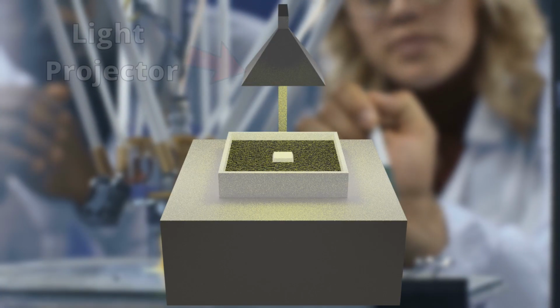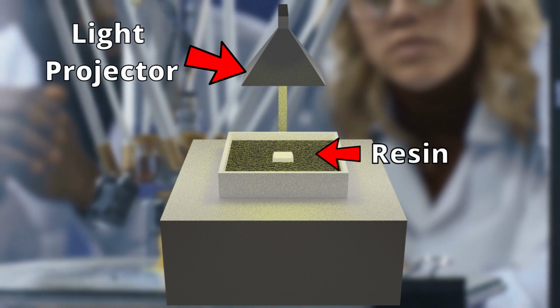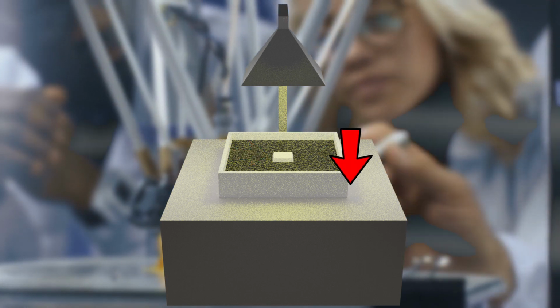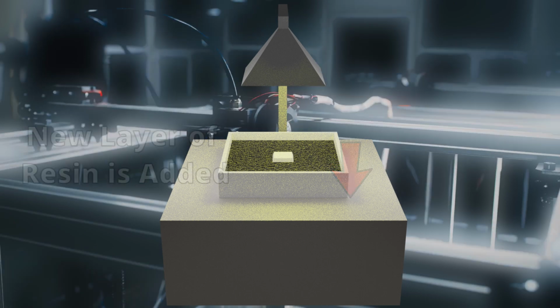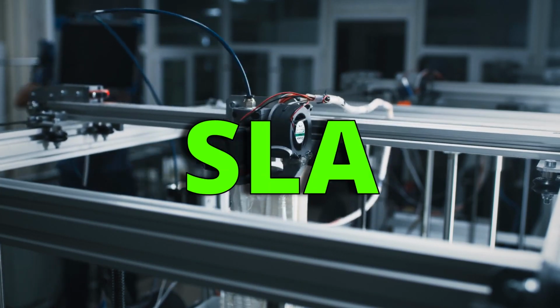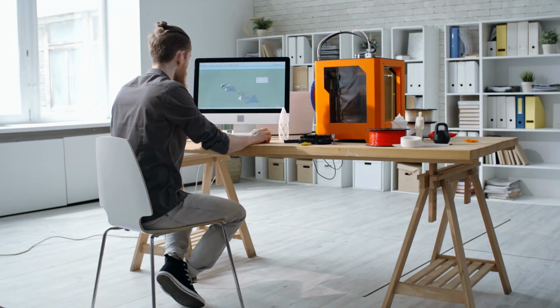In DLP, a light projector projects over the build platform where the liquid resin is placed, which is sensitive to light. The light solidifies the resin, forming a solid layer. The build platform then descends by a precise amount and adds a fresh new layer of liquid resin. This process is repeated layer by layer until the entire object is completed, while SLA, instead of light, uses a laser, and that laser traces each layer one at a time, not all layers at once like DLP does.